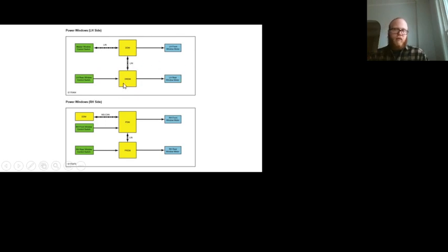They don't go back and forth. It's just a way to send out a little bit more complicated information. Versus an MSCAN, where the driver's door module and the passenger door module can actually talk back and forth in that case, which is more convenient for sure, but more expensive. So it's just walking that fine line between functionality and cost, basically. All right, and with that, we end our lecture.